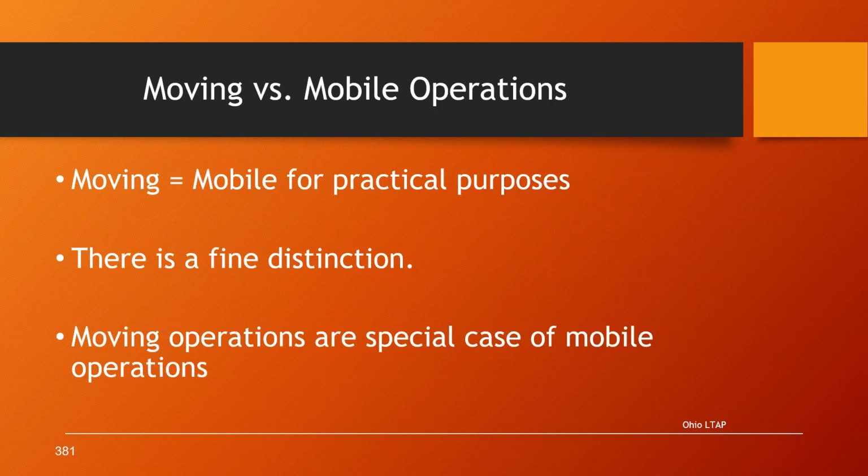So moving versus mobile operation. Moving and mobile, they're the same for practical purposes, but there is a fine distinction. Moving operations are a special case of mobile operations. So mobile would be where you might be stopping for a while and then continuing on. So moving is when you're actually moving all the time, like pavement marking, striping.